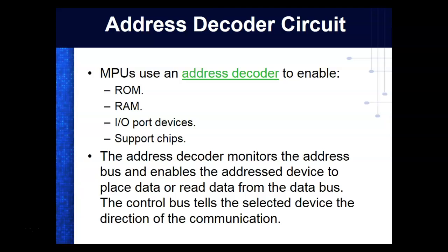So I can select an IO, an input, by using I, so that tells the processor that I'm using an input. Then we'll put a code. And then we're going to select a module number. Since ours are integrated right now, our modules are going to be 0 because they're inside the PLC. Does that make sense? And then I'll put a slash, and then I'll put a bit number.